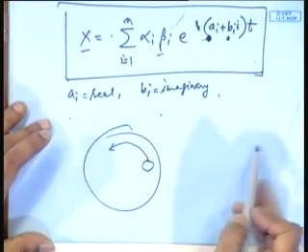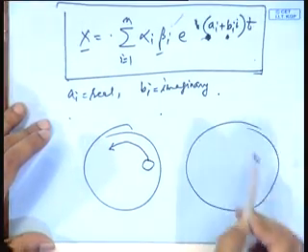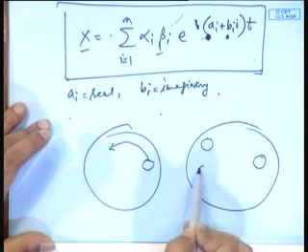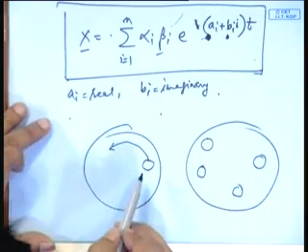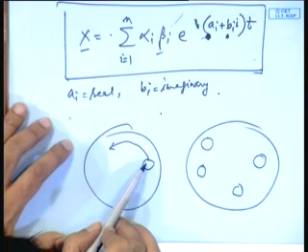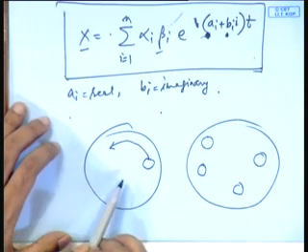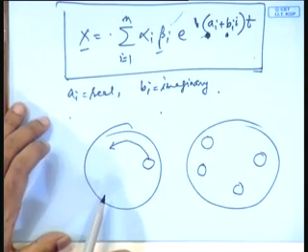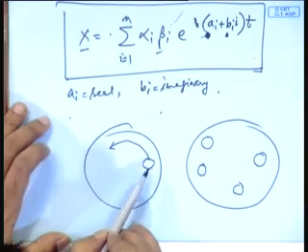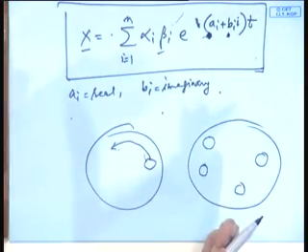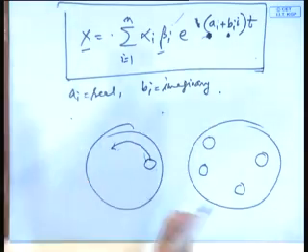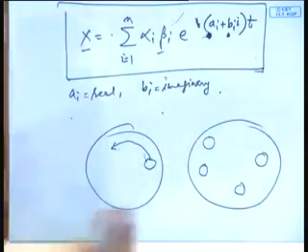When you study these systems theoretically, we assume there is a hotspot over here and another hotspot emerging and another hotspot emerging and so on. But in a real system that does not happen. What happens is that these hotspots start to travel, because there is an imaginary part, a cos and sine part of it, and there are oscillations. As they travel, they gain in size, and then it leads to a huge hotspot, and then there is a whole explosion, the reactor blows up.